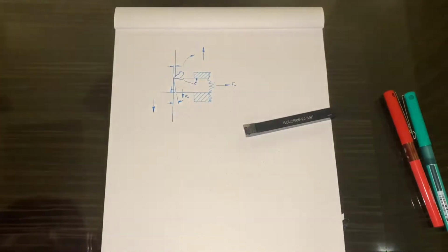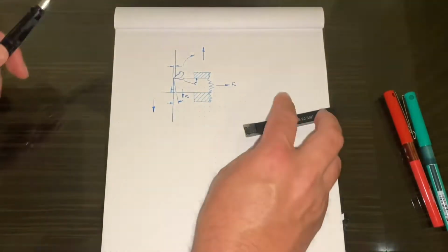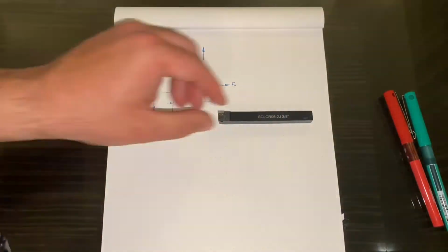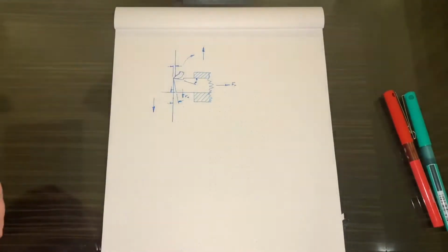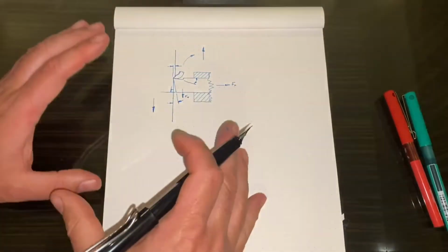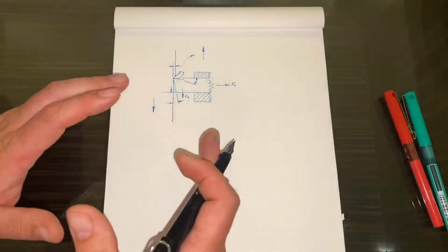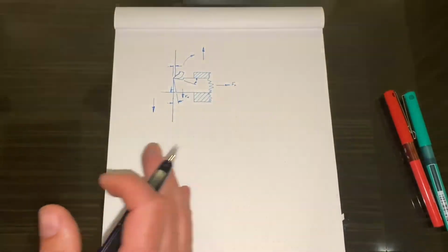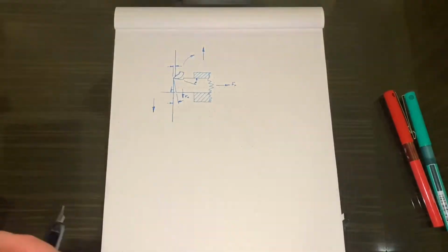But for unhardened ductile materials, we'll always use positive rake. Okay, so the reason for explaining that is because it's easier to visualize what's happening here when machining a flat surface, so planing or shaping. But all of these principles relate directly to turning, and I'll explain why in a minute.